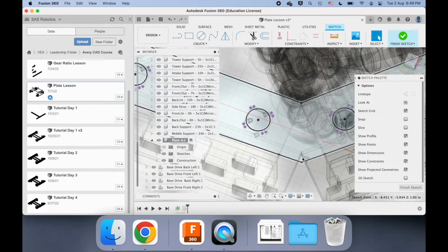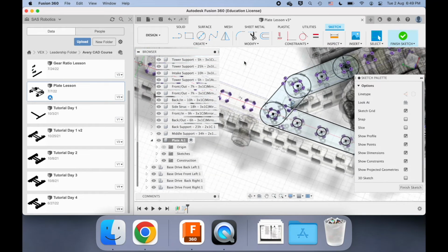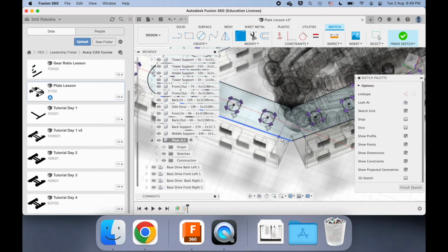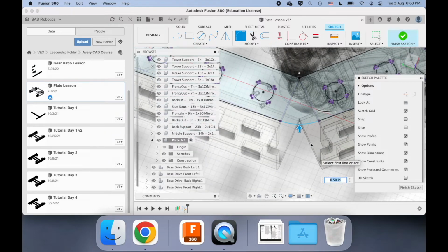And so with that in mind, we're about to see this when we use this tool called the fillet to round corners like this. And let's say I want this to be a 0.5 radius because that's what some of the other dimensions are, right? 0.5 this.